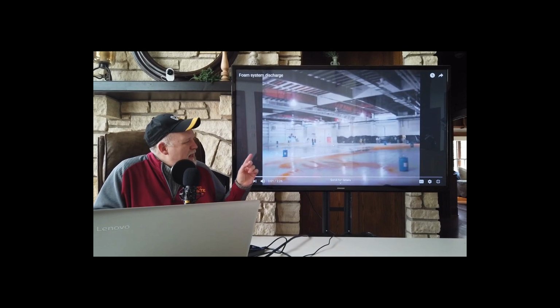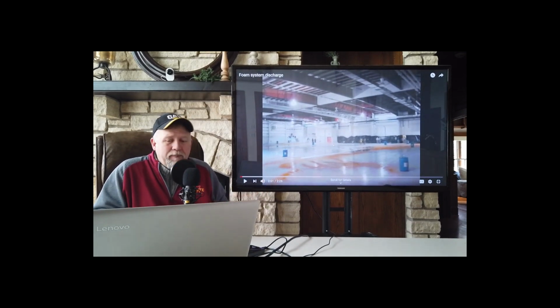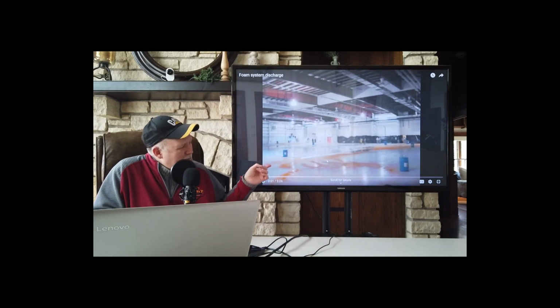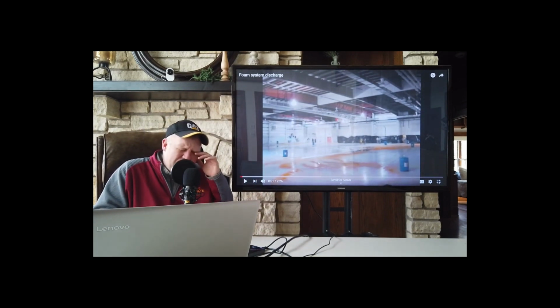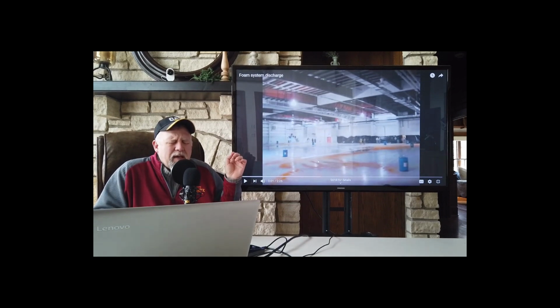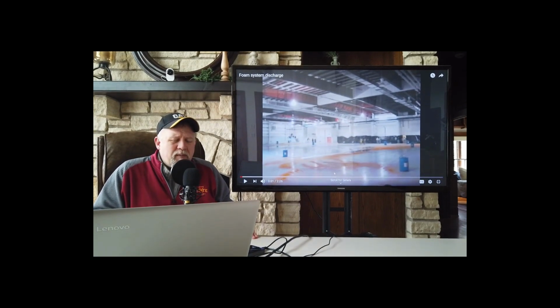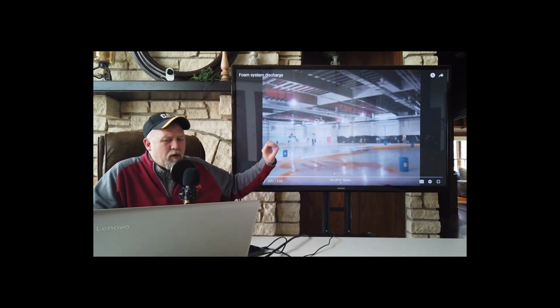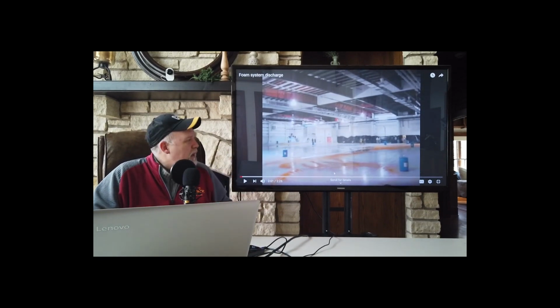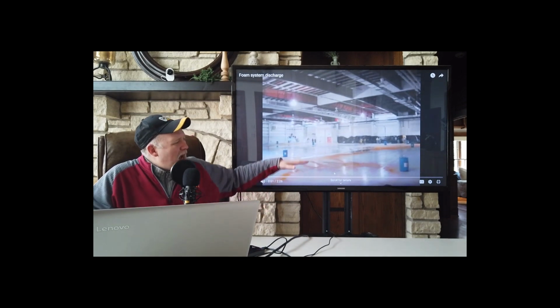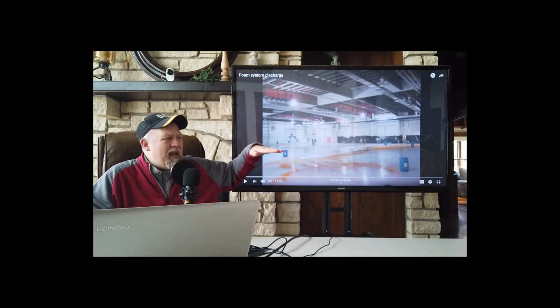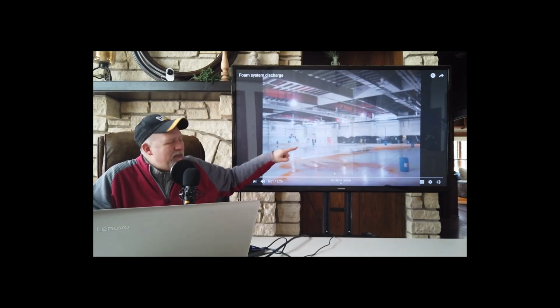Specifically, and this happens to be an aircraft hangar, and this test was actually done in Des Moines. I've only designed a couple of these systems. One of them was for the Waterloo National Guard, where they kept the Black Hawk helicopters, an aviation hangar for that. And I learned a few things about these foam systems. The foam systems are designed specifically for a room and for a specific aircraft. In other words, you design it so that it discharges foam high enough that it covers the fuel tanks for whatever aircraft you have in the hangar.